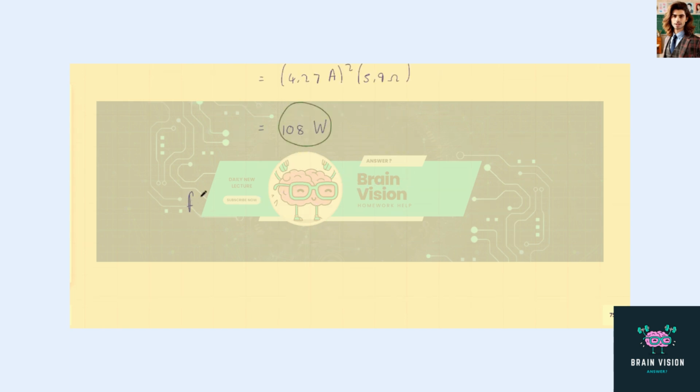Now for part F, we want to calculate the power input. So the total power input is equal to V times I. So that's VAB, 120 volts, times the total current drawn, 4.82 amperes, which gives us the total power input to be 578 watts. So that's the total power input of this motor.